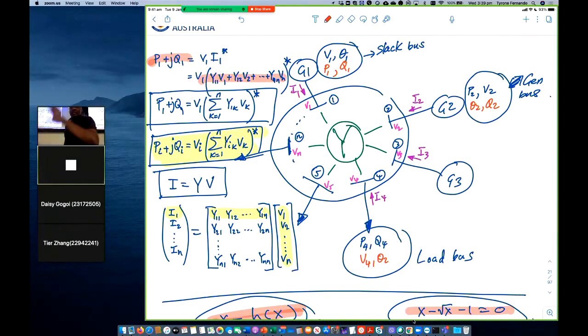Because the admittance matrix multiplied by the voltage vector, the first row. First row of the admittance matrix multiplied by the voltage vector. That's that term in the bracket. Of course, I've taken the conjugate because we want the conjugate of that current. And then we can write that in compact form. I've written that below with a summation. That's just writing the same expression in compact form.